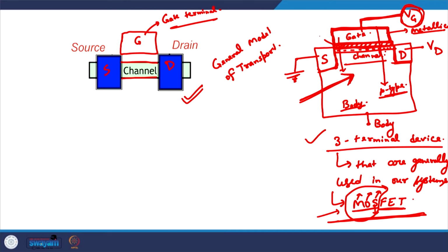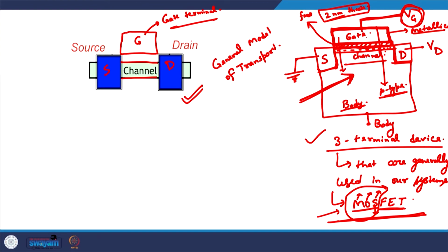Although this oxide nowadays is only a few nanometers thick, it might be around 2 nanometers thick, and some electrons, if sufficient energy is available, and in some conditions, if they can see empty states in the right direction, can tunnel through this.